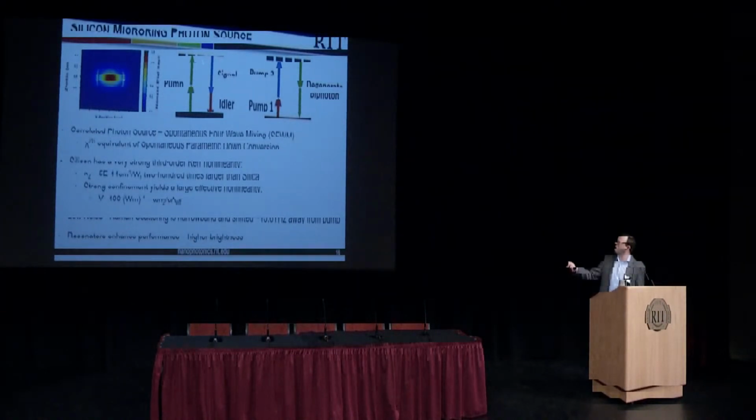So that pump laser, which pump usually is taken as a term meaning that you need a lot of light, but silicon waveguides are so small that with only even nanowatts, you're able to actually get a very strong nonlinear interaction that is producing plenty of photons.